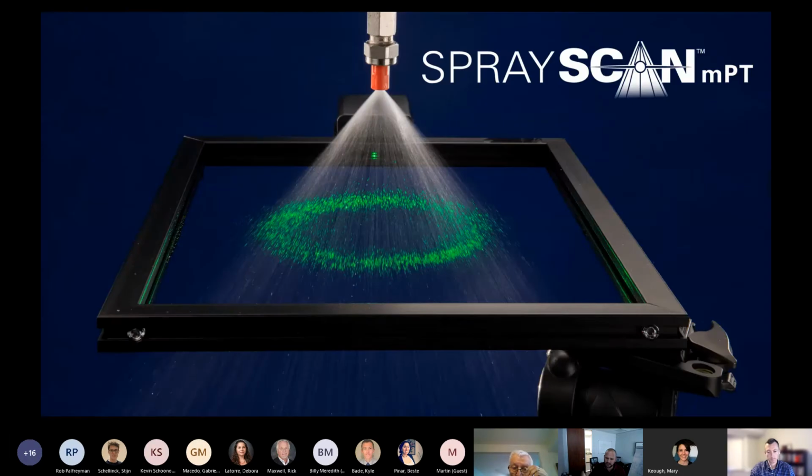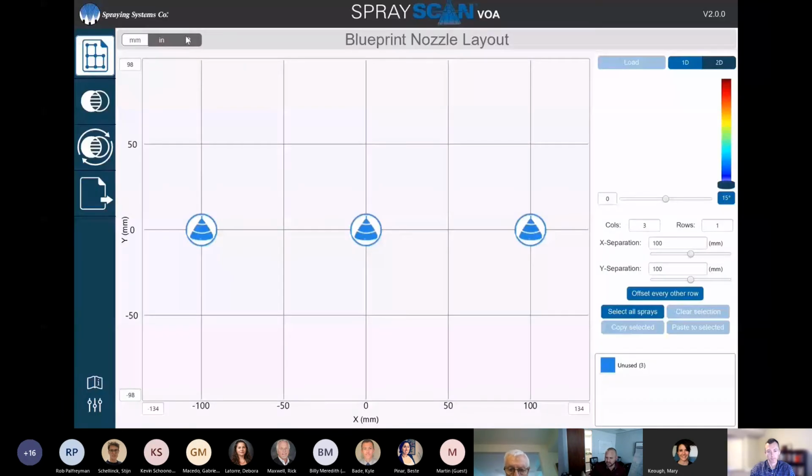And Kyle, can you speak a bit too to even distribution towers or trays that we would see, in a circular orientation? How could that be a benefit for somebody in the processing industry? Absolutely. You have a given flow rate that you need to put through a tower, for example, and then where do you position these nozzles to adequately cover the entire environment, use the entire tower effectively, right? You don't want to have dead zones. You also don't want to be hitting the walls where you have potentially buildup of material or at least wasted material that's not interacting with the gas stream. So having a good idea of where that spray is going to be going and where to place those nozzles ahead of time is what this software allows you to do.